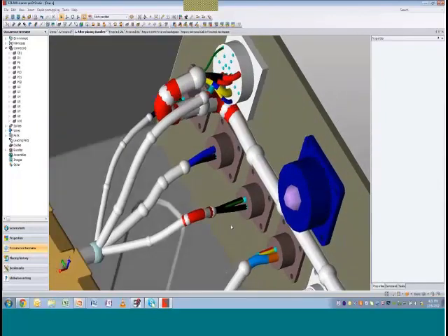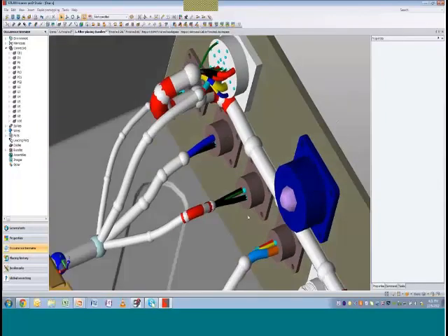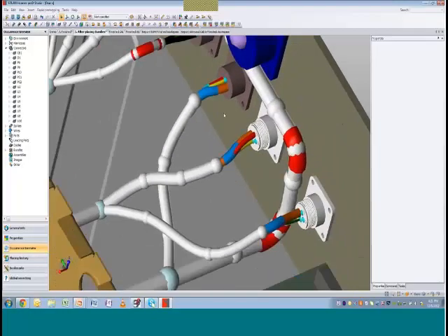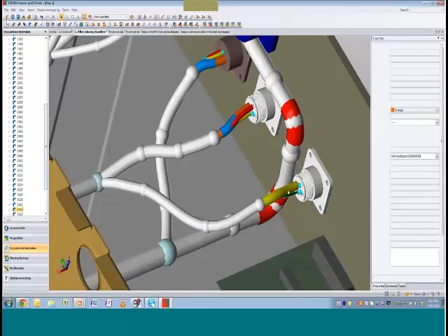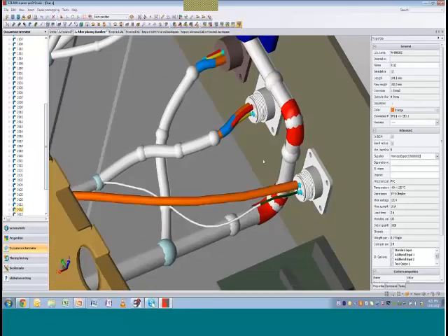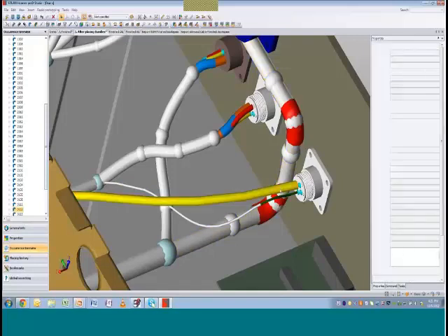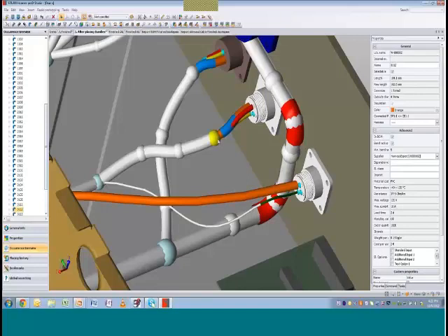If I want to change the bundle, if I want that wire to go in through a different origin, I can easily select a wire and unroute it, and now that wire is not routed anymore. You can see the bundle actually shaped itself. It changed its shape according to the actual size of the wire. So if I wanted to change the route of this particular wire here, I can show it going to a different route, or I can manually move that to a different route.